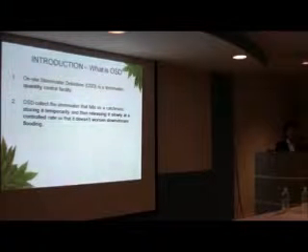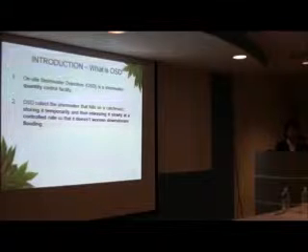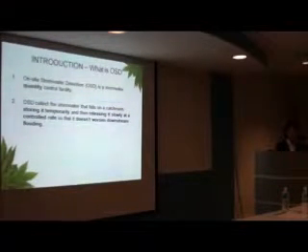The functional principle for OSD is it collects the stormwater that falls on a catchment, stores it temporarily, and then releases it slowly at a controlled rate so that it doesn't worsen the downstream flooding. It will not solve the existing flooding problem, but the intention of OSD is to give zero impact from new development.